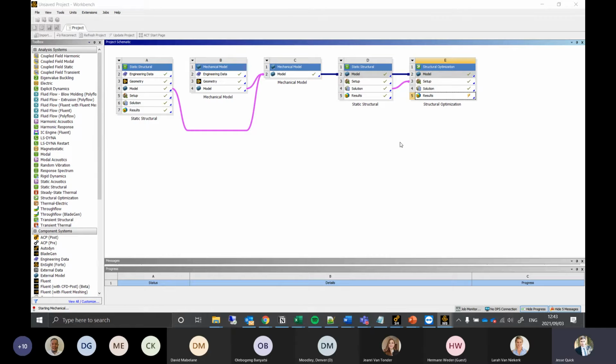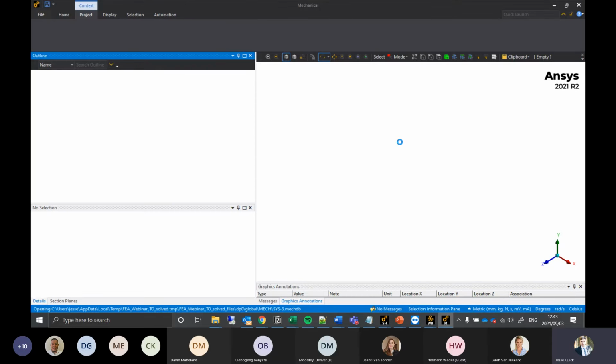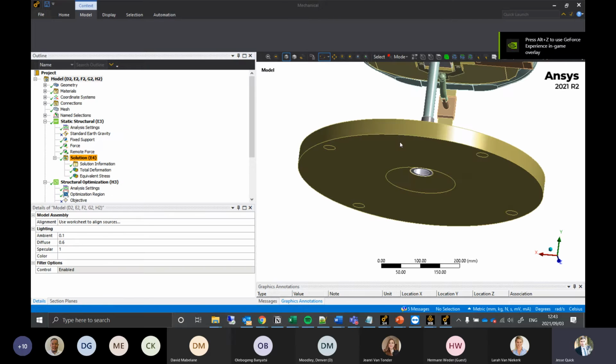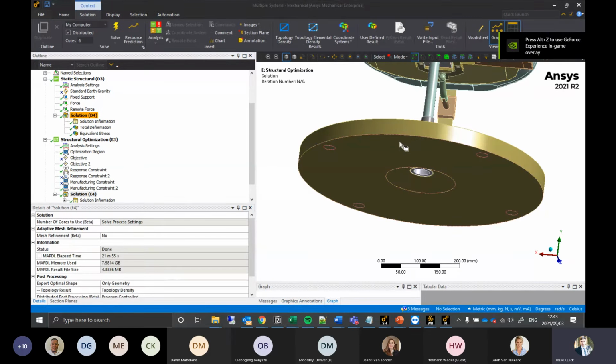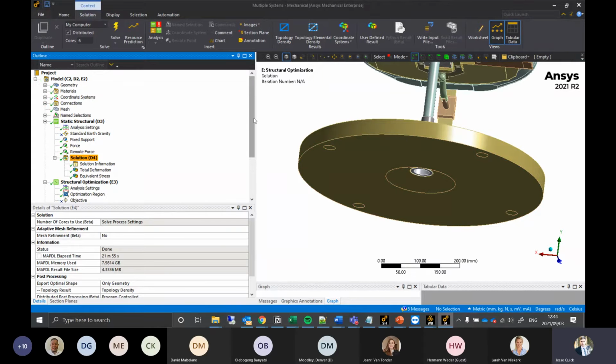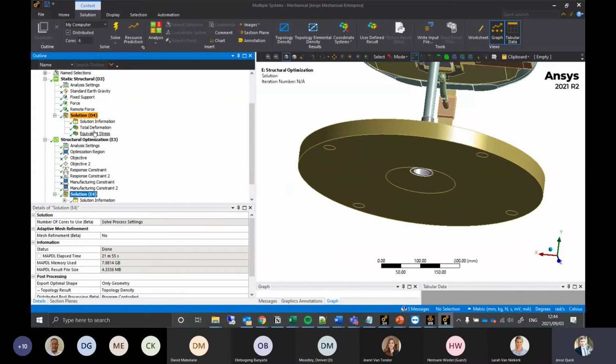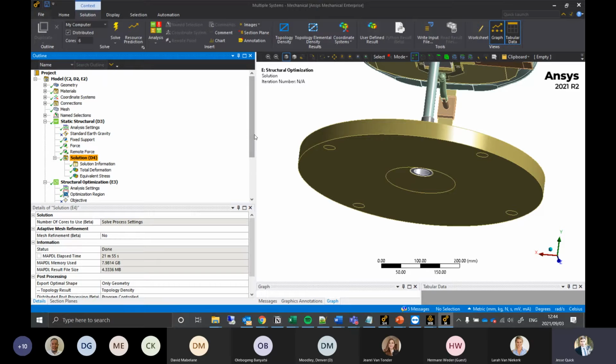So what it does is the topology optimization starts off with all of the elements enabled. And then it identifies elements that are not actually carrying the load along the load path, and it removes them using this density-based method. So I was playing around with a couple of additional constraints over here, mainly for the member size and so on, just to see what interesting shapes I could get.